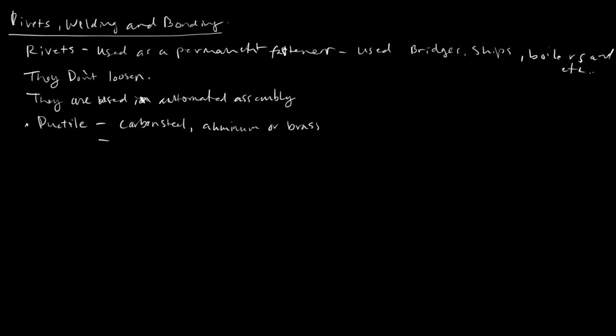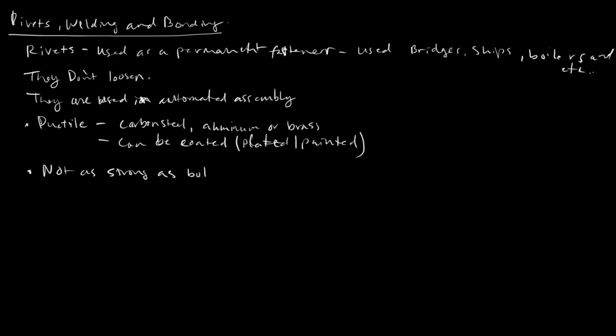And obviously they can be coated or plated or painted to get them to last longer and be less corrosive if they're used with dissimilar materials. They are not as strong as bolts for the same diameter. And there are many rivets to choose from.